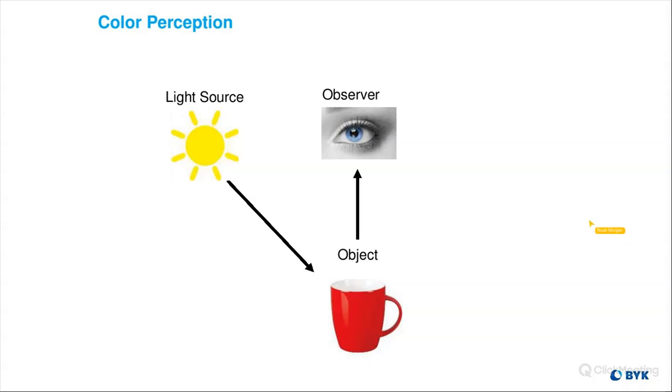So your light's coming in from the side and it's hitting this white coated surface, the sphere, and bouncing around until it eventually hits the sample and illuminates the sample. And then the reflection of that sample is scattered through the white sphere until it hits the sensor inside of that white sphere. I know that was a lot. Like I said, the presentation we go over has visuals for what I just said, and it's a lot nicer to listen and look at. But the big picture is they don't correlate. It's two very different types of measurement systems. One's using direct light, one's using diffused light, and so you're not going to get correlating results with that.